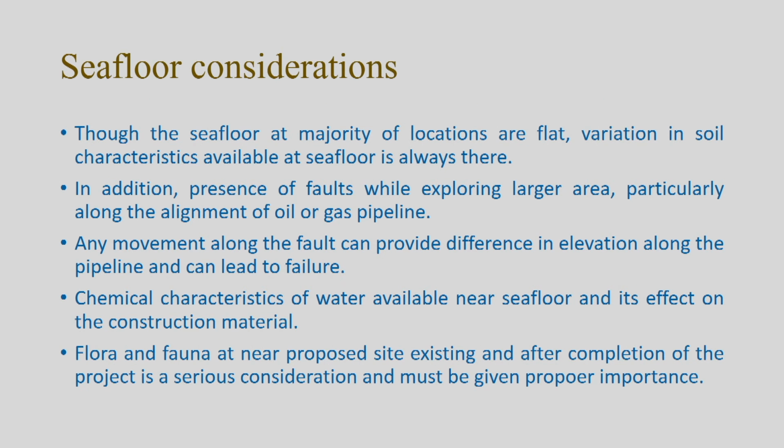Now, seafloor consideration. This is very important here. Though the seafloor at the majority of locations is flat, the trenches and seamounts which I told you about are available at specific locations, but not throughout. So, most of the time you find seafloors are very flat. However, there will be significant variation in the subsoil characteristics at the seafloor. It will be varying along the depth and also laterally.